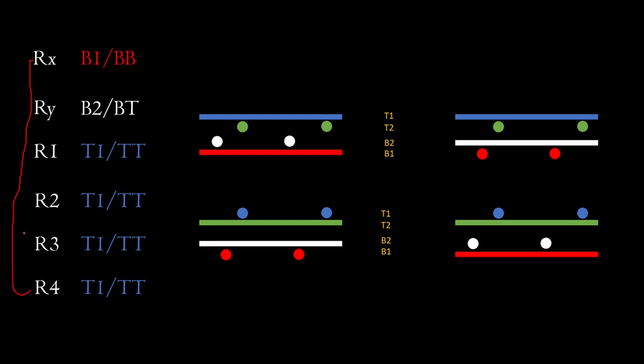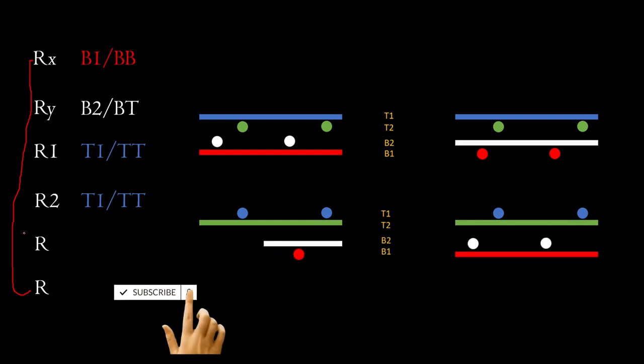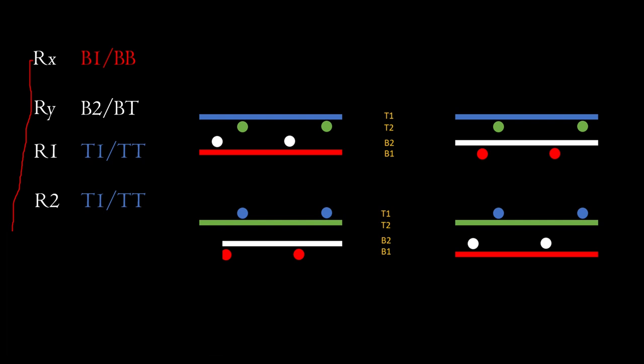But in a one-way slab, the most important component is the reinforcement that is provided along the shorter span, and in this case, is going to be Rx. So reinforcement Rx is the reinforcement that we place at the bottom position and is always going to be parallel to the shorter span of the slab.